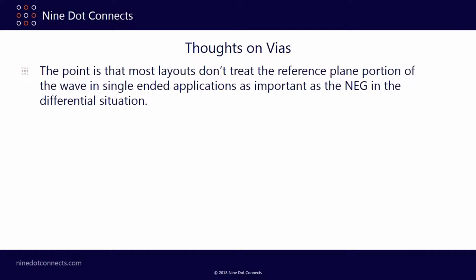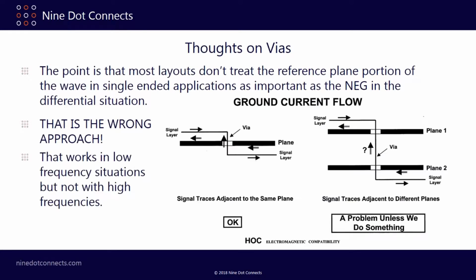Most people don't treat the reference plane portion of the wave in a single-ended application as important as the negative in the differential situation. That is the wrong approach. It's going to get you in trouble. It might work in low frequency situations, but it's not going to work in high frequency situations.